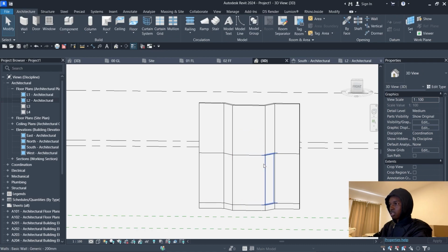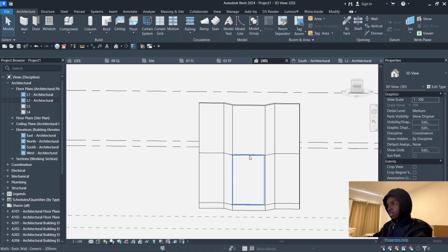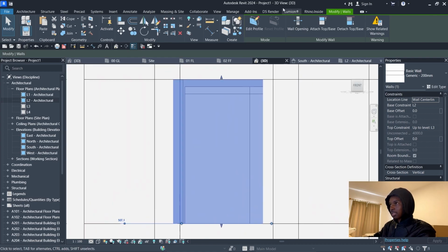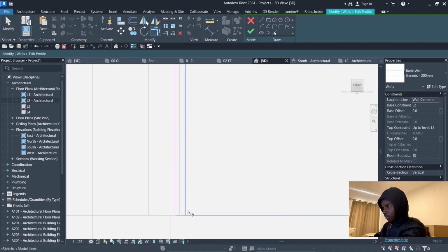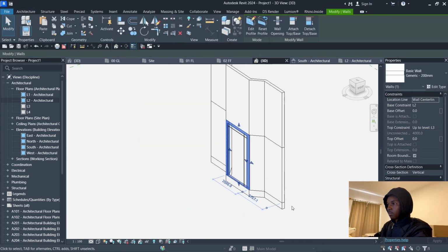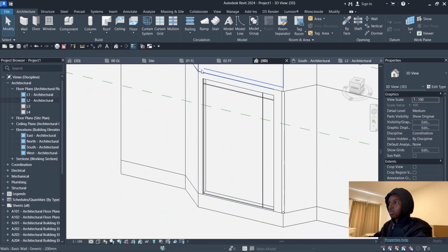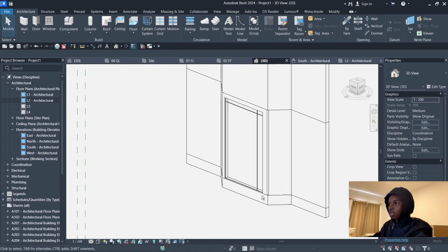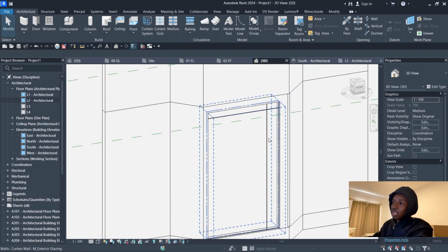So what you guys did was, you cut this wall. That's not a way to work with curtain walls. This is how you guys did it. You select this, edit profile, highlight the curtain wall, and delete this. So trim this off. This is what you guys did. Then you have your curtain wall here. Then you can see the curtain wall. This is not a proper way to model the curtain walls, because now you have this gap here, and then other gaps will show when you add all the other sides with this curtain walls. And you already had these grid lines here, which I don't want.